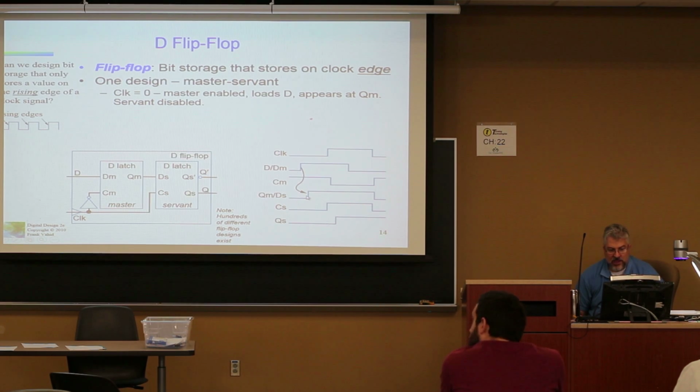At a certain delay, you'll get Q out. That serves as the source for this latch here. And based on the rising edge of that clock, that's when you will then clock this information, specifically the data that came out of QM. That's when you'll actually be latching that through to the QS.